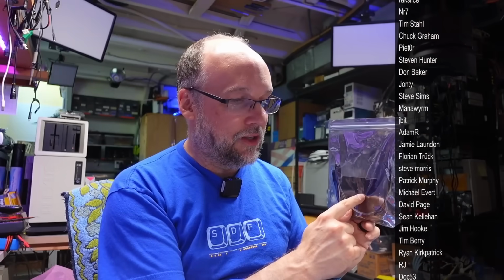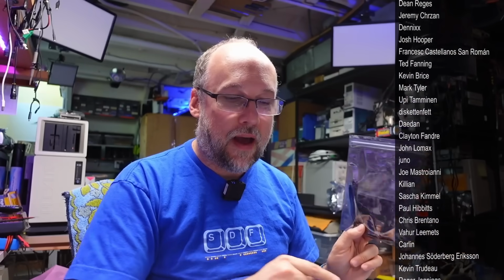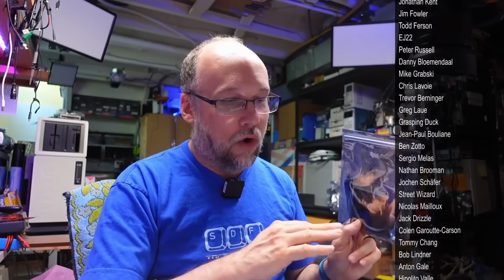It was awesome to be able to use this very inexpensive logic analyzer to be able to identify exactly what's bad, so I didn't have to go and do a whole bunch of chip swapping or buy parts that I don't even have. Like I don't have an extra 8031 CPU, for instance. That's why I absolutely love getting to the bottom of the fault first before doing a whole bunch of chip swapping.